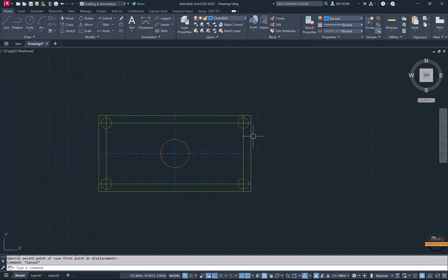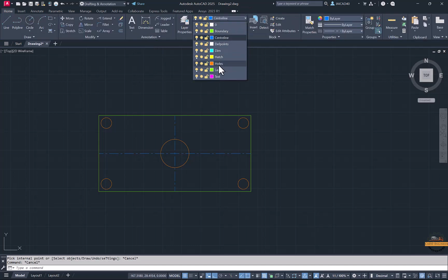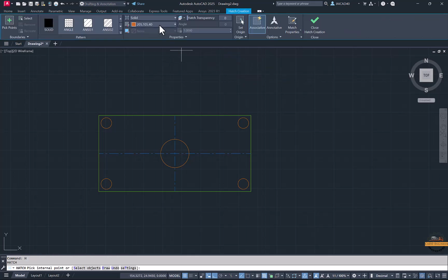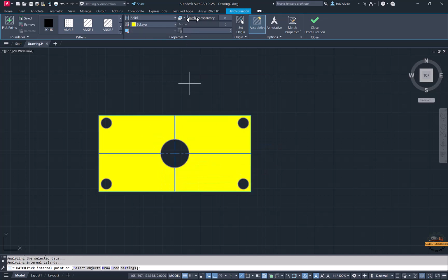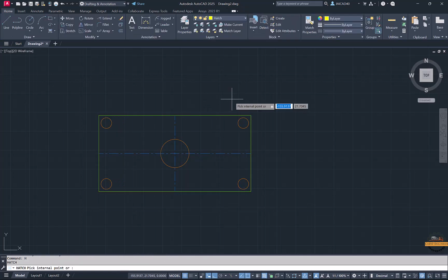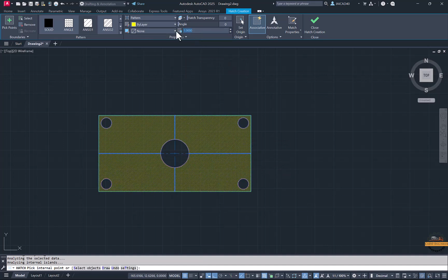Now I want to put hatching in this area. So we can do hatch, H enter. For that we can use the hatch layer. So we can assign a layer here. Let me set the layer to the hatch layer. Now H enter, I'll pick here by layer, and we can select that, and we can specify the color, the angle and the scaling of the hatching that we require. Once we've done the hatch, it's set by color. Let me take some pattern. So I'll take some pattern here. Now I can fill in the pattern value.